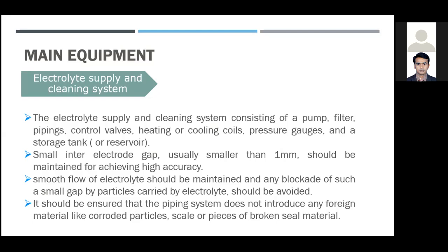Smooth flow of electrolyte should be maintained, and any blockade of such a small gap by particles carried by electrolyte should be avoided. It should be ensured that the piping system does not introduce any foreign material like corroded particles, scales, etc.